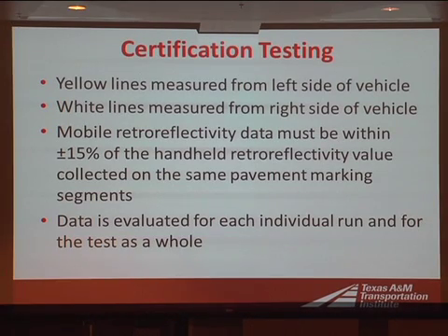One of the things we also test when we're doing the certification program is we actually evaluate the accuracy of the contractors' handheld retroreflectometers as well. We started that a few years ago when we ran into some issues where different contractors and actually even pavement marking manufacturers had handhelds that weren't properly calibrated and needed to be serviced. So we started monitoring those handheld retroreflectometers as well, because if you're using a piece of equipment that's not operating properly to calibrate your mobile retroreflectometer, then your mobile retroreflectometer will not be able to collect accurate information.